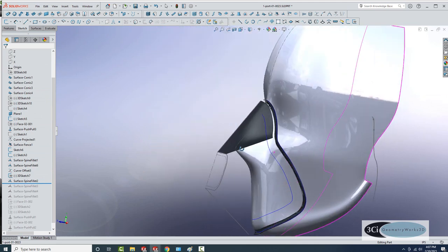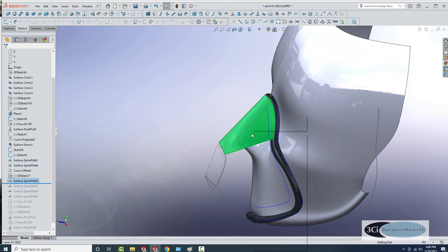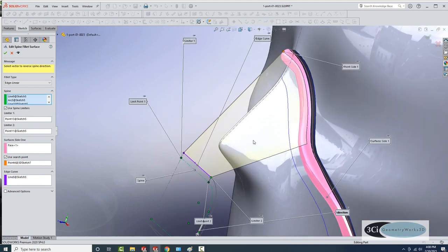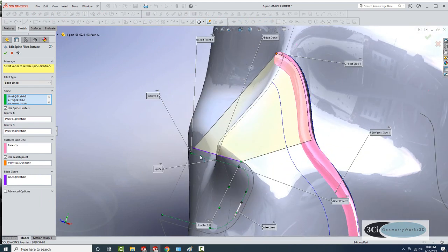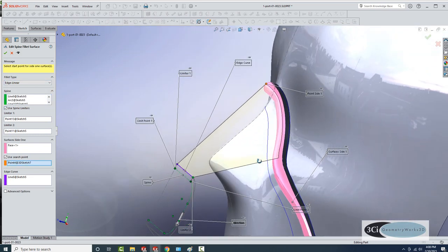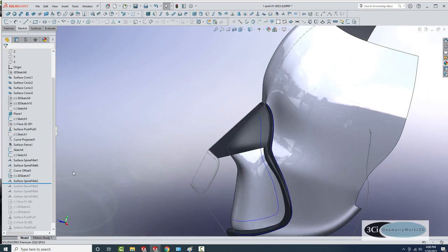Now we're going to create a linear surface between the line, which represents the face or the box, and the tube surface, which was swept previously. This is again the fillet spine driven surface, and this time it's best to use this tool to develop the curves. So we're taking it in small bite-sized pieces. I'm interested in finding the edge of this linear surface as it comes in contact with the swept tube, which is actually on the face.